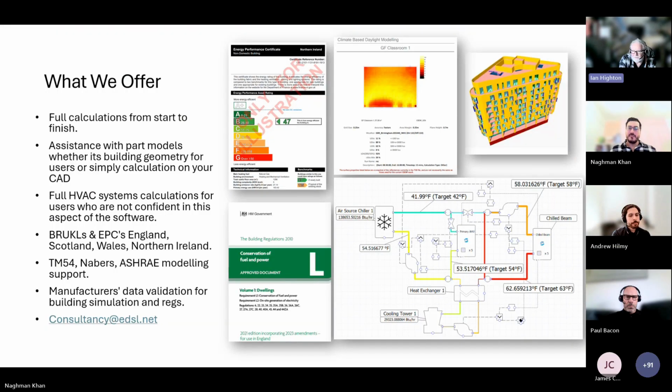You can just literally drag across a number of components, create a group, and then you can drag that group into the library on the right hand side, and it will turn up as a new item in the library which you can give a name to. That library persists across different models and different projects, so you can just pull it back in again, ungroup it and start to edit. So it's quite a flexible system in terms of transferring pre-built schematics via the library into other models and other projects. Yeah. Let's take a couple more questions and we can wrap up.